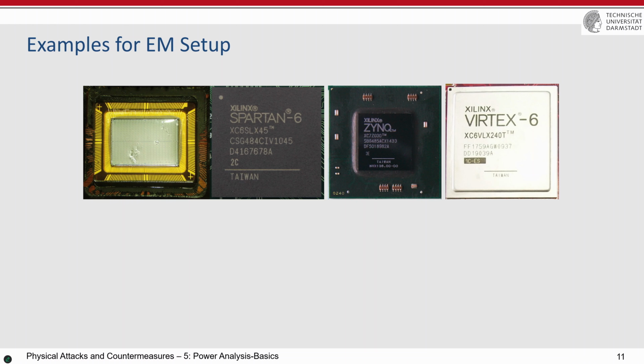This was a bonding technology, and another one is flip chip. Flip chip means something like this, there is no bonding wire at all. This is the back side of the silicon, of the semiconductor. This is the front side. This is the back side. It means that the package is designed like this. This is the package. This is much larger than the semiconductor. The semiconductor is designed, the pads are there, and then the chip is actually flipped over the package and is glued on the package. There is no bonding wire, no soldering, nothing.